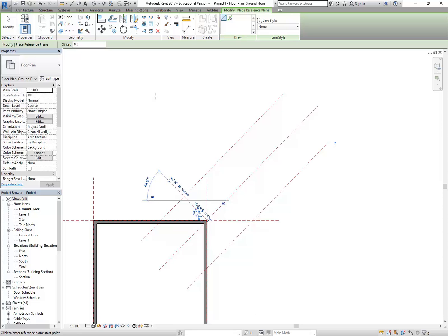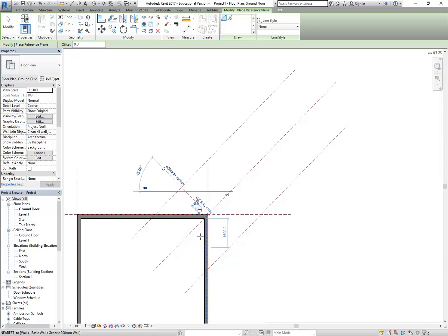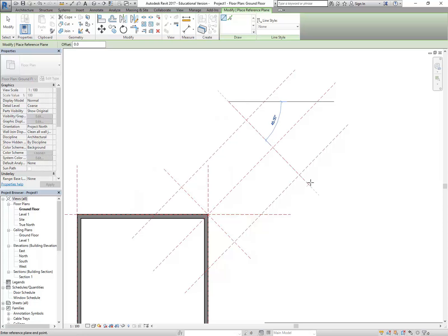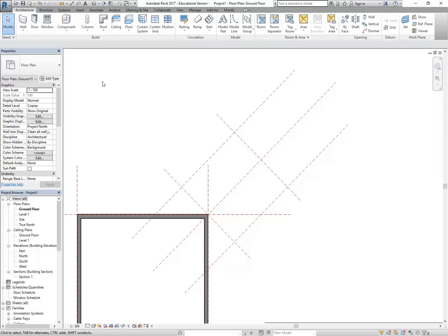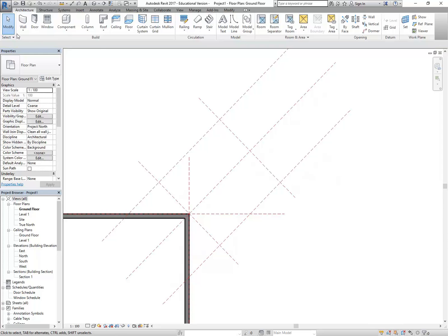Again, I've just drawn it with the angle I want, and now I can extend it by dragging the corner or the end at the bottom out to cross over the reference planes. Yep. So I'll just do one more step and I'll come over. So now I can draw a plane out in space that's also 45 degrees from the baseline there, parallel to the last one, and change the measurement to 4,000. So it's just like you do with your set square and your clutch pencil when you're on a drawing board.